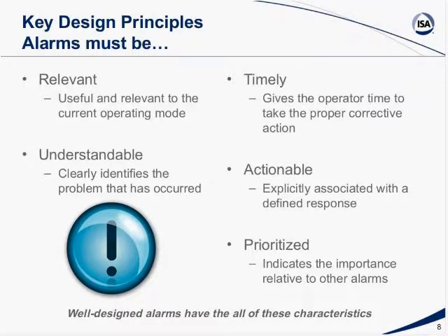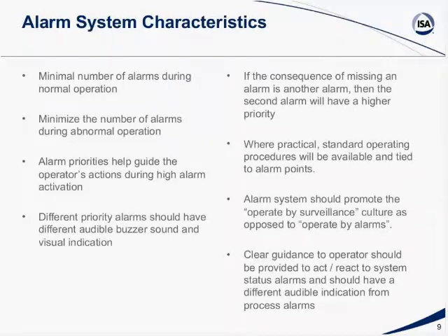All alarms have to be actionable, okay, meaning that there's a very specific thing for the operator to do. And I'm not talking about go make a cup of coffee or anything like that. There are very specific actions that the operator has to take to bring the system back to normal operations. And the alarms have to be properly prioritized, and we'll cover that in some detail as we go forward. But these are the key design principles. All alarm systems need to have these characteristics, okay?